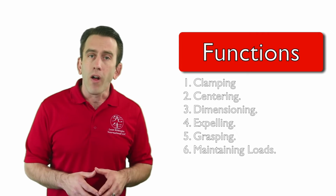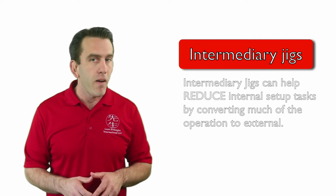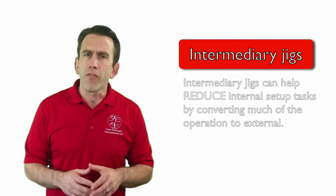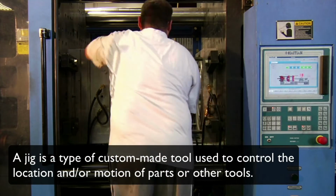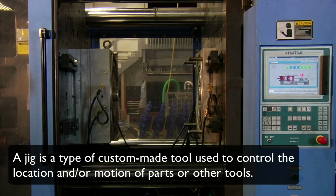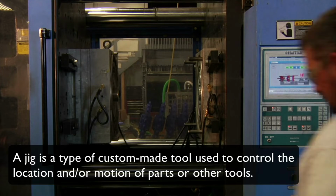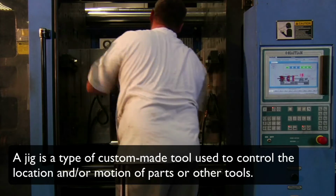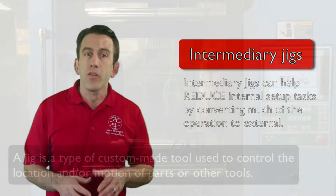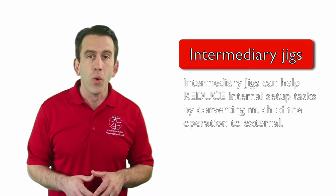Another way that internal activities can be reduced is through the use of intermediary jigs. A jig is a type of custom-made tool used to control the location and/or motion of a part or parts or other tools in a setup. In this case, a custom jig can be made or purchased to quickly attach tooling. Oftentimes, if the jig is standardized, it can be left on machines so that tooling can be attached even quicker.